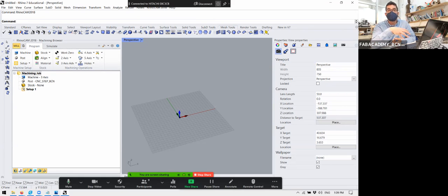With a CNC, you're working with, let's say, big toys and serious toys. You want reliability at 100%. For example, the software that runs a 3D printer can run a CNC, but it's not the same as these small CNCs. They use, this one is Marlin, a basic firmware for 3D printers, and this one uses GRBL. The difference in firmware is about reliability. In 3D printers, the firmware, at some point, in like 0.0001% of cases, can lead to a failure. A failure in a 3D printer is not as catastrophic as in a CNC. Here you need way more reliability and security in how it accelerates and how it moves. So the base code, from mechanics to firmware, is in general way more robust in CNCs.